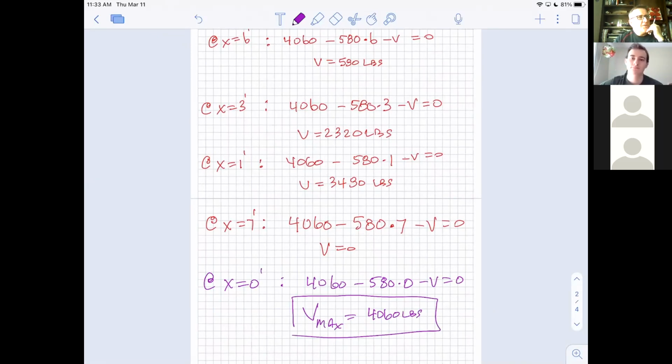Now let's go back to that sheet. So the shear maximum, the maximum shear required by our little design we just made, and that's a super common beam design. It's what I design in houses every single time. It's that exact design. So now can you choose a beam that's big enough? Notice allowable shear. Where's a beam in there that is not going to shear off right at the end where the post is supporting it? Notice none of the beams that are 1.5 have a big enough answer for that question. This is the first one.